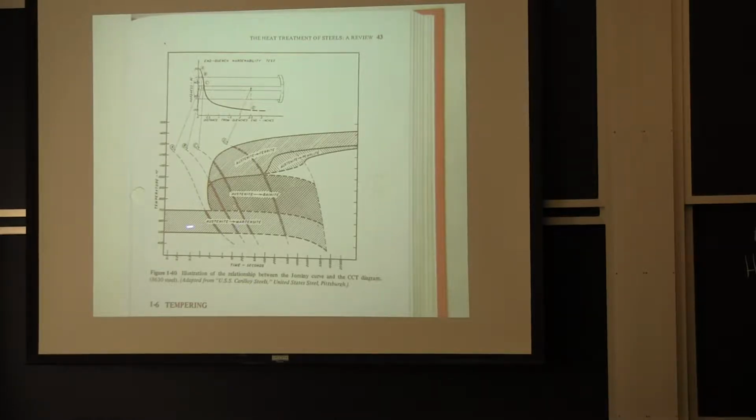It turns out the austenite to martensite is a somewhat unusual type of transformation. It doesn't just occur in iron carbon alloys, it occurs in nickel titanium alloys, some copper-based systems, a number of different systems have martensitic phase transformations. The martensitic phase transformation is basically just a shearing or displacement of the crystal lattice. So it goes from one structure to another. And that means it occurs at something close to the speed of sound.